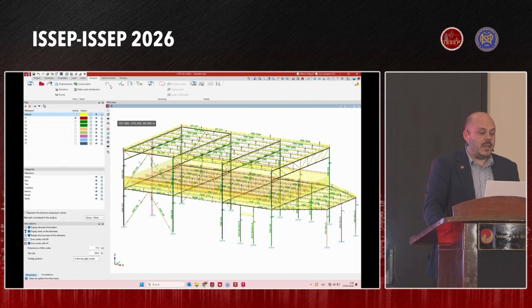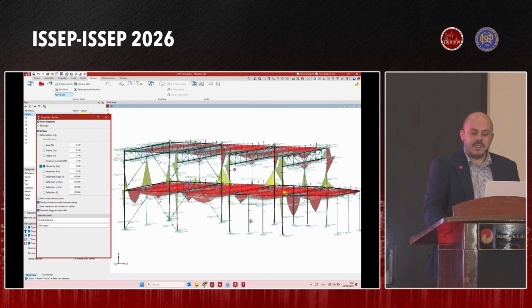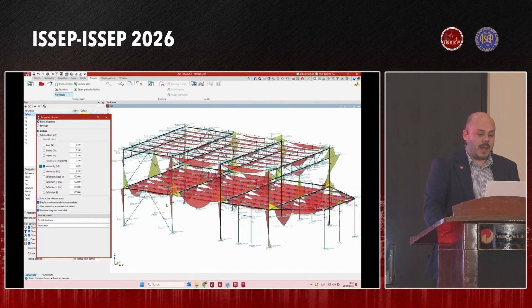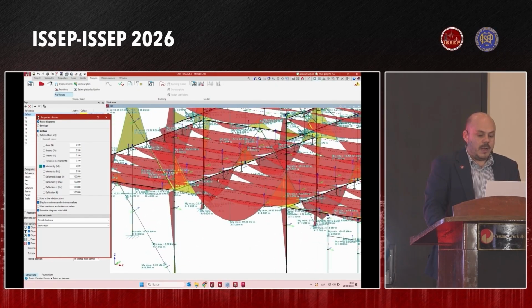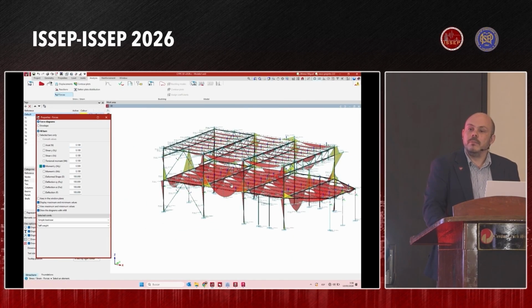This project, I already analyzed it. So for example, here I can see some forces, some moments that I'm applying here, moments that we are generating here, not just the moments, also the shear, axial forces, also other information related to the deformed shapes of the structure. So this is an analytical model. This is analysis and design.